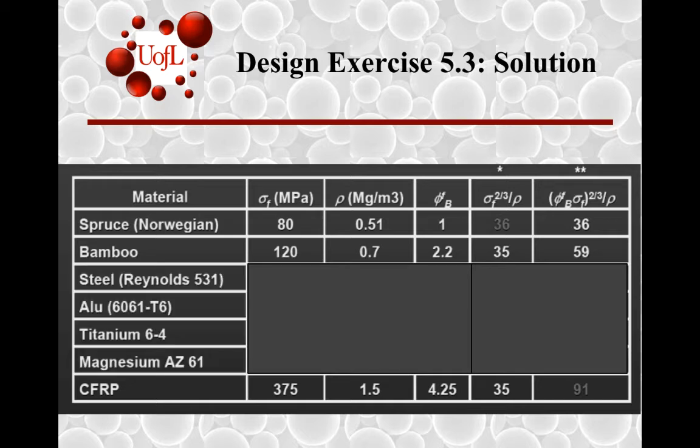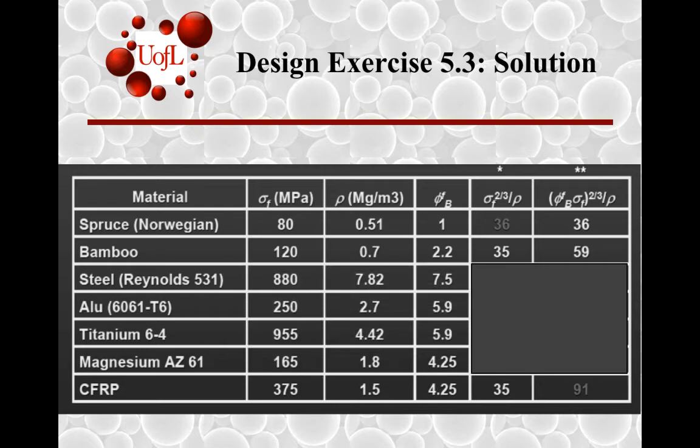What happens when you look at 4 other materials, one of which is steel, and the other 3 are lower density materials: aluminum, titanium, magnesium, which are used in engineering structures. Steel, of course, has the virtue of having a much higher failure strength, but also the highest density. Suppose you had these values of shape factors for this particular case to failure.